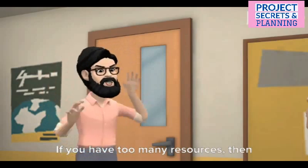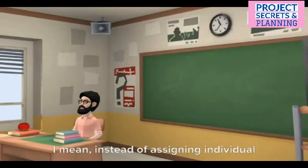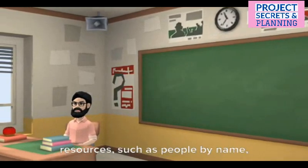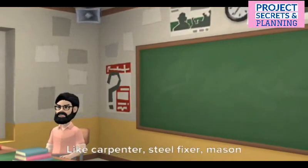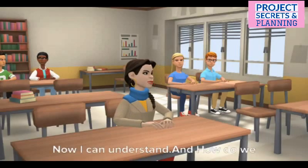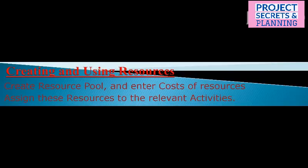If you have too many resources, then you will definitely be in problem during updating. I mean, instead of assigning individual resources, such as people by name, use their skill names. Use crews or teams, like carpenter, steel fixer, mason, etc. Oh. Now I can understand. And how do we create resources? In the resource tab of Primavera, we create different resources skill-wise, and assign these to their relevant activities.